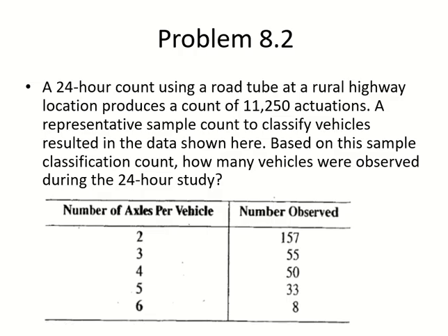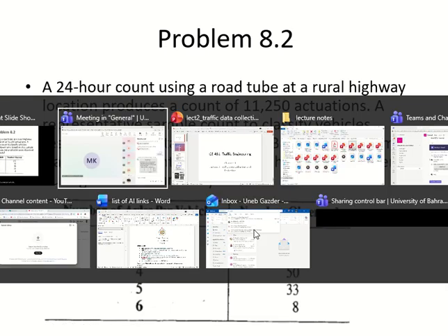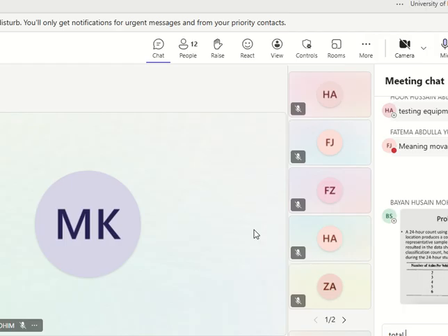I did a manual study, let's say for 5 minutes. In those 5 minutes, I had some vehicles which had 2 axles, some with 3, some with 4, some with 5, some with 6. The factor I am looking for is the number of axles per vehicle. I want to calculate the number of axles per vehicle so that I can convert this count into the number of vehicles. So from this manual study, I will do total vehicles upon total axles.